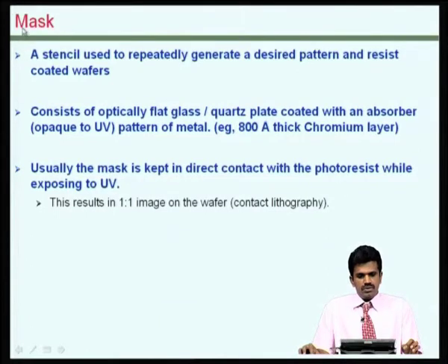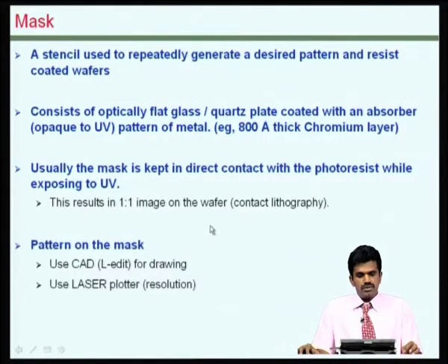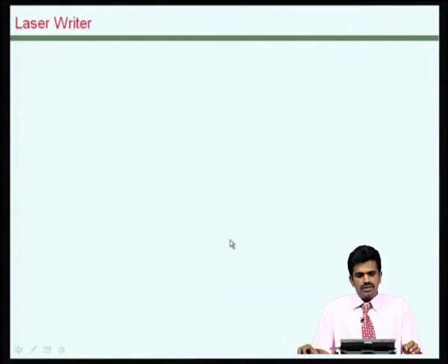So, creation of the mask is also critical, and these are usually done by a 1:1 transfer of an image, which is first created using a CAD tool. Typically, people use a commercial software known as L-Edit, and several laser based plotting or writing schemes are available for transferring patterns onto the mask.